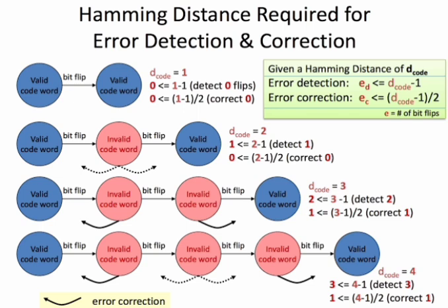Frequency of local oscillator is given by, for down conversion, FLO = Fs − Fif. For up conversion, FLO = Fs + Fif, where Fs is the carrier frequency of the desired AM radio signal. Up conversion is preferred because of requirement of less tuning range. For AM, polarization is vertical and wave propagation is ground wave. The tuning range of local oscillator is 995 kHz to 2055 kHz.